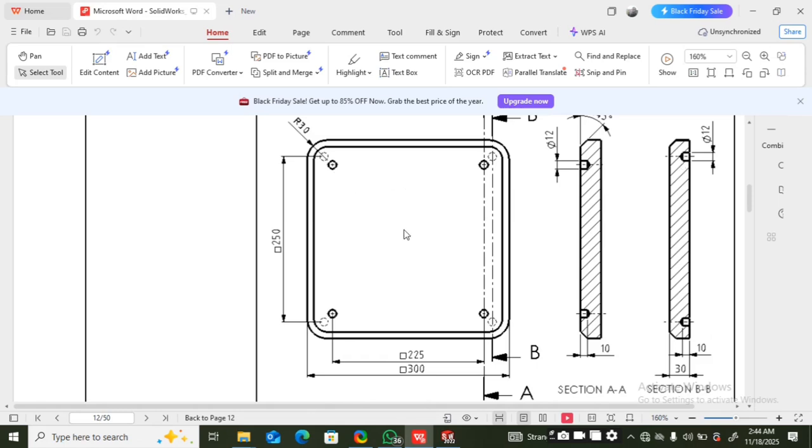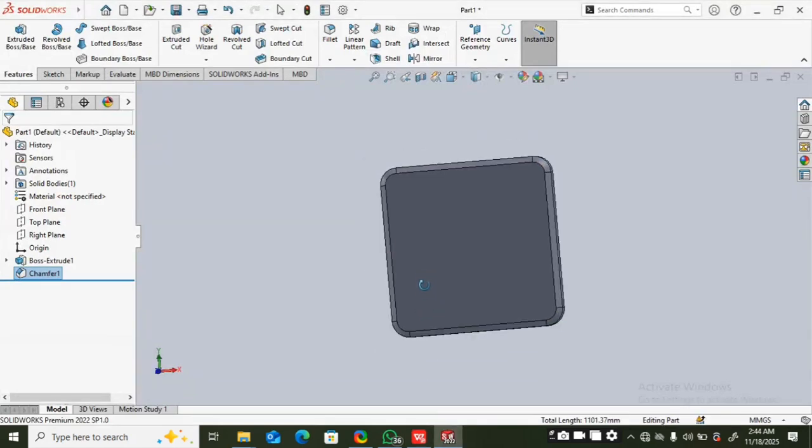Now you can see there are two distinct sets of holes there, and they need to be designed according to their respective spacing. The space between this hole and the entire set is 250, meaning it is spaced by 250 millimeters, and the holes below the plate are specified as 250. Sorry, this is 225 and 250.